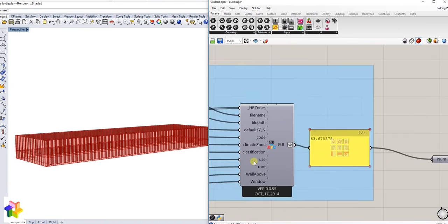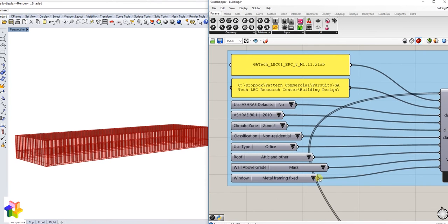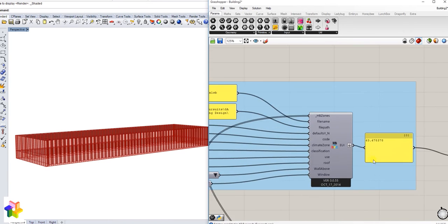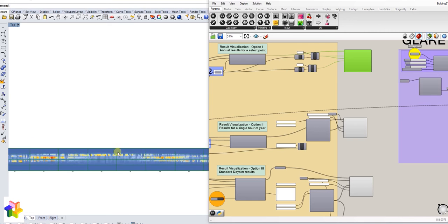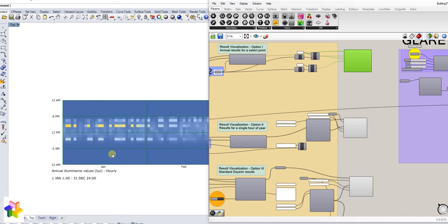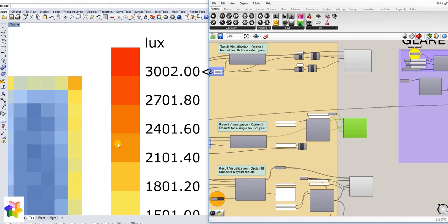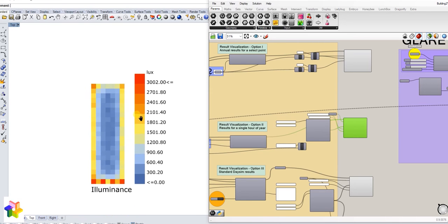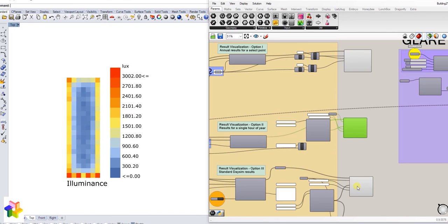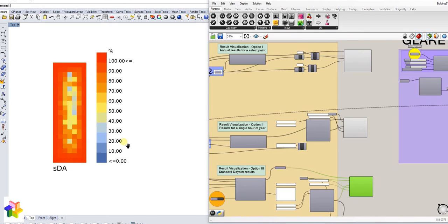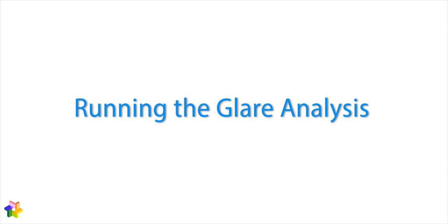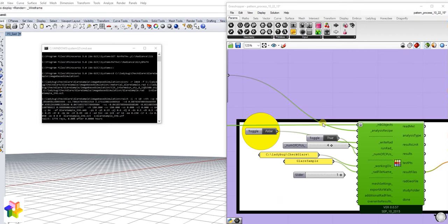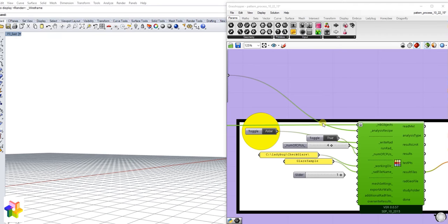As we start looking at the energy and the daylight parameters, we can look at yearly maps for daylight to try to see exactly where we're having some trouble. This is a yearly lux map, and this is a lux map for a specific date, similar to what LEED requires. Here is a spatial daylight autonomy map, and daylight is never complete without a conversation about visual comfort. We start looking at the daylight glare probability for varying interior viewpoints.